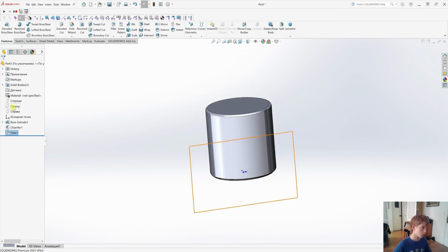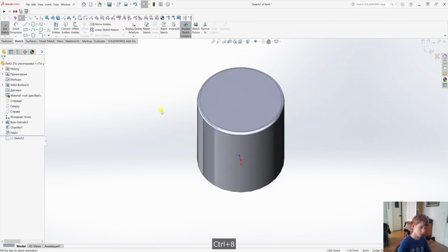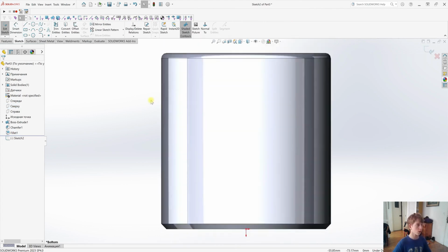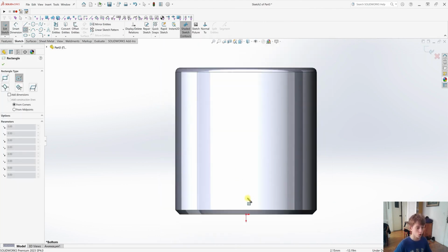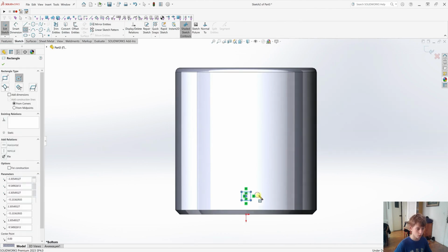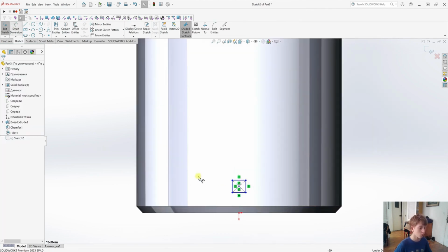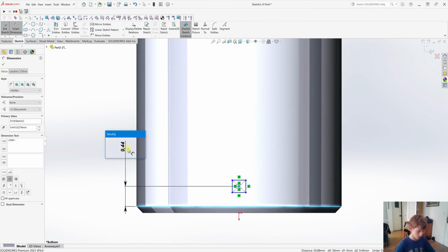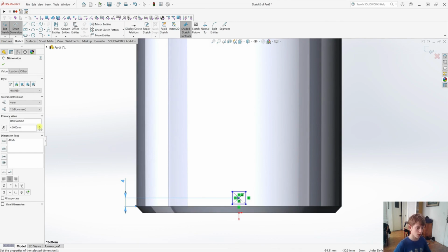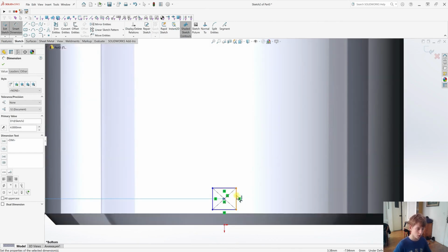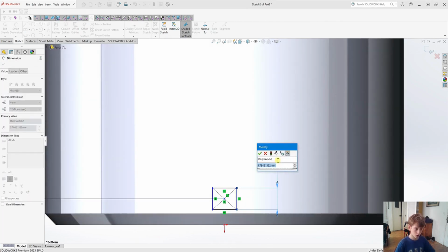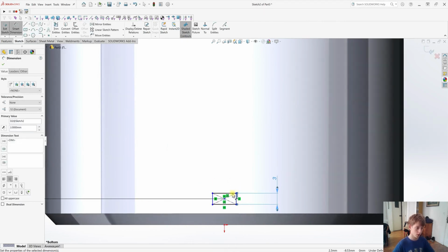Now I'll draw a sketch on the top plane. Now I'll carefully switch the side and draw a square right from the center. I'll set the distance from the bottom edge to a value of 4 units. After that, I'll adjust the layout so that it forms a grid with 3 rows and 3 columns, making it a 3x3 arrangement.